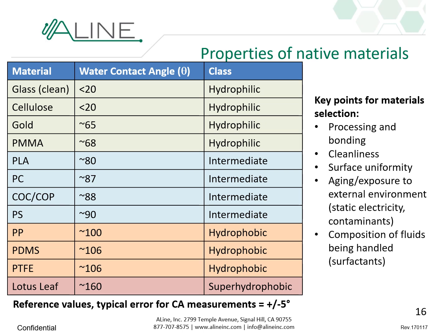And then moving on into higher contact angles, we have the hydrophobic group, where you have polypropylene, PDMS, and PTFE, or any type of fluorinated Teflons that are hydrophobic with contact angles typically in the 3 digits. And then if you go into the higher level, lotus leaf, this is typically 160, and that's what's typically defined as super hydrophobic.